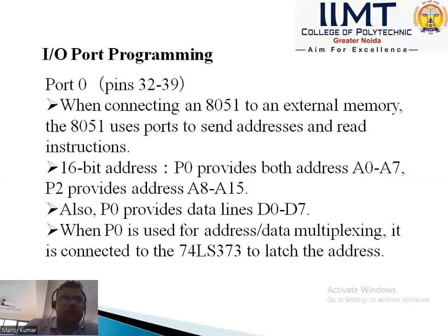Input output port programming. Port 0 is pins 32 to 39. When connecting the 8051 to external memory, the 8051 uses ports to send the 16-bit address and read the instruction. P0 provides address A0 to A7, and P2 provides address A8 to A15. Also, P0 provides the data lines D0 to D7.